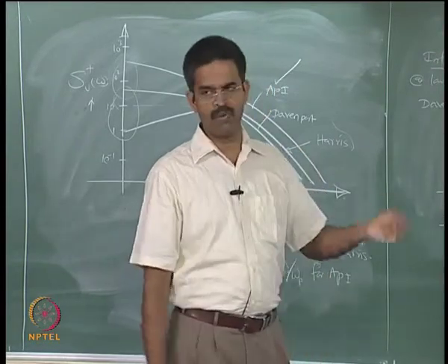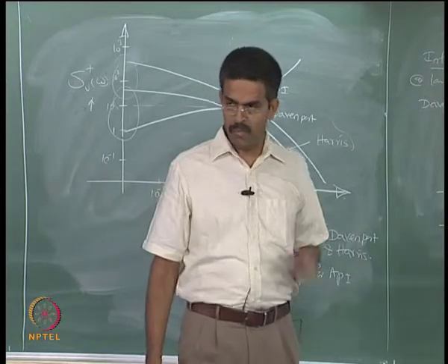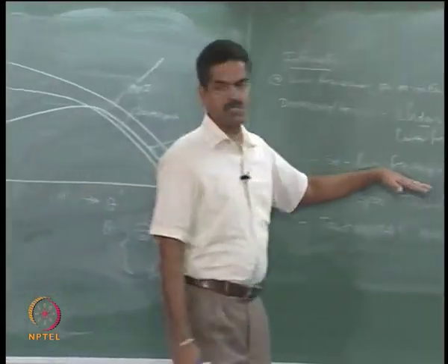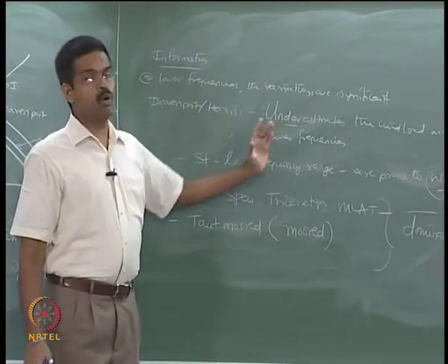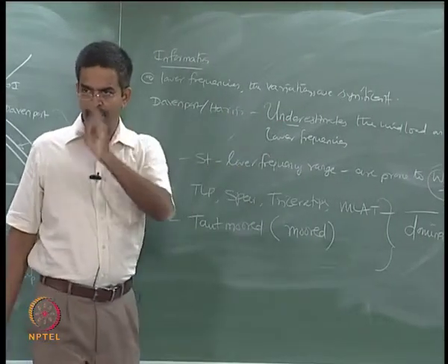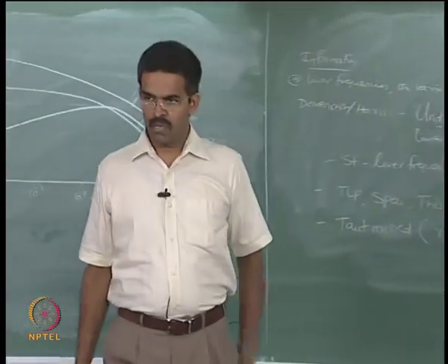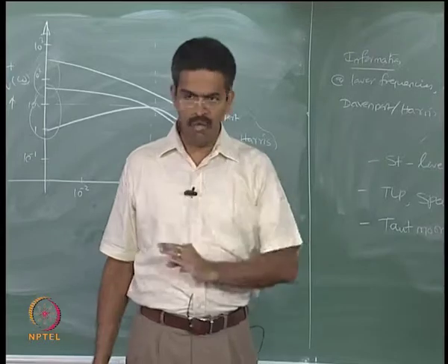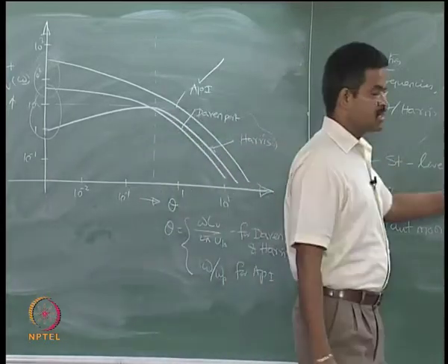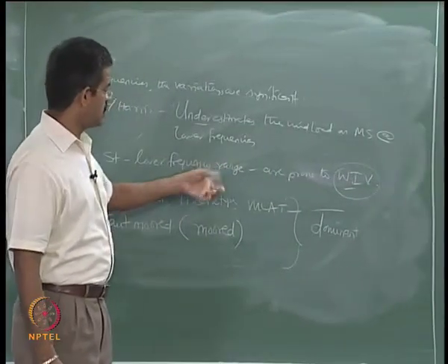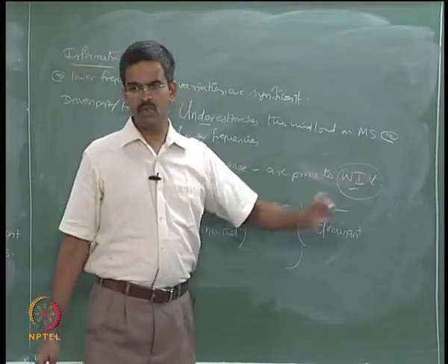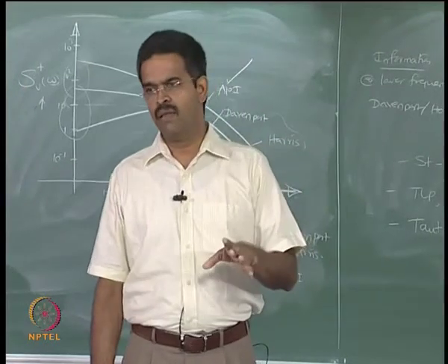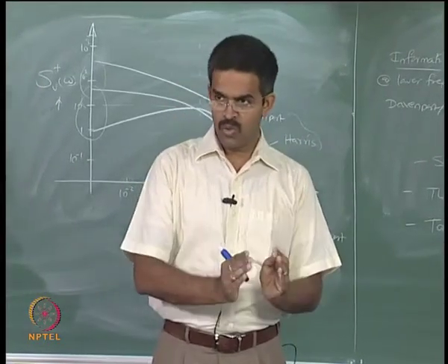So generally codes prefer quasi static analysis, but it is very important that structures with low frequency range account for the dynamic amplification from the gust component of the wind load, because this can cause wind induced vibrations. Therefore I must know how to handle the gust factor in my account.